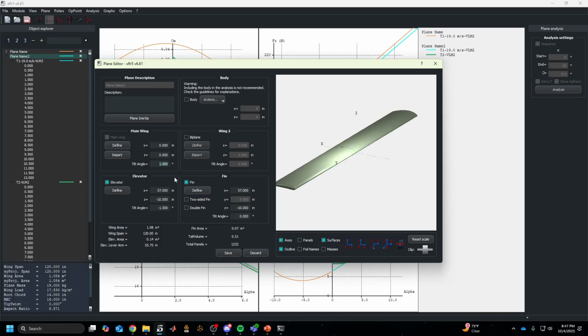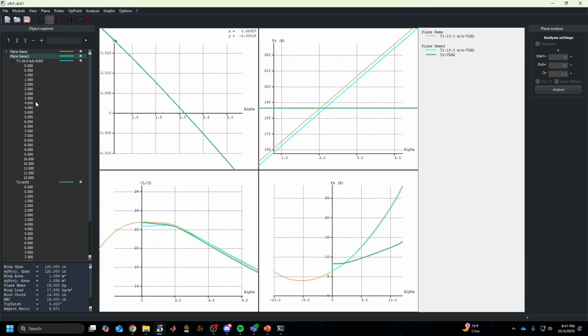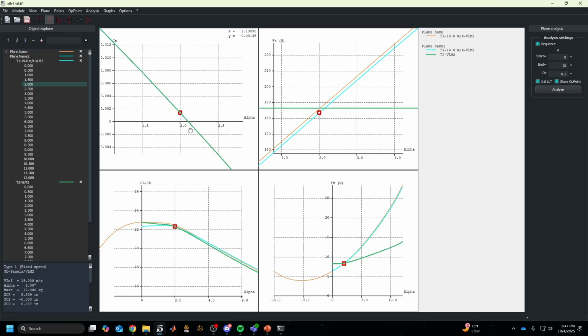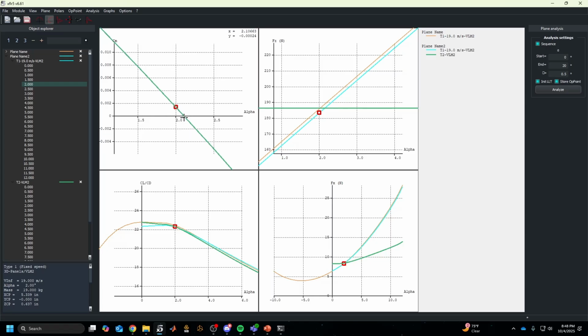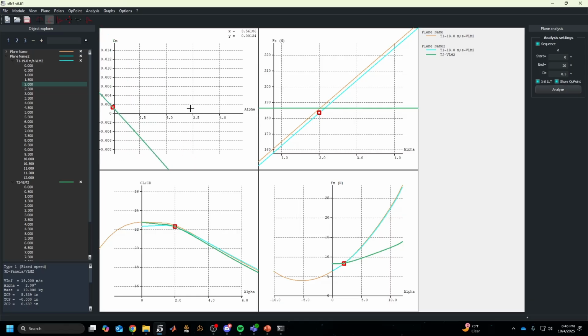Right now it's on 1.5 degrees, but if it were 5 degrees, and I was looking at my trim alpha, and we're trimmed at 2 degrees alpha, then my actual wing alpha, which is the thing that matters, is going to be at 7 degrees alpha. Since we have a 1.5 degree angle on our wing, we're at 3.5 degrees, right? 2 plus 1.5 is 3.5, okay?